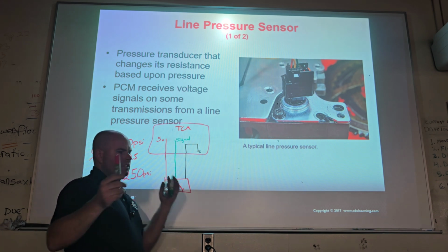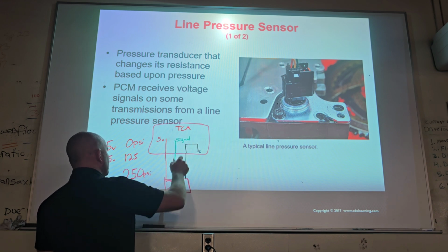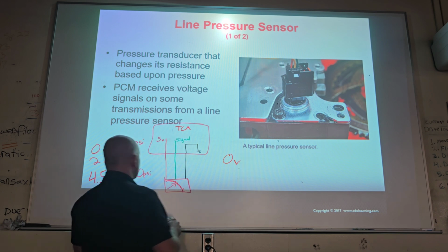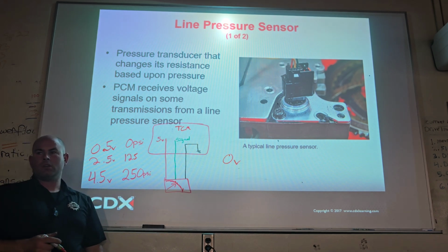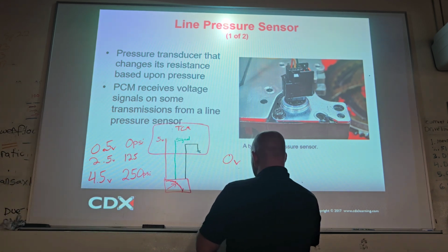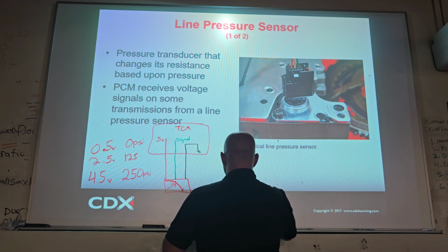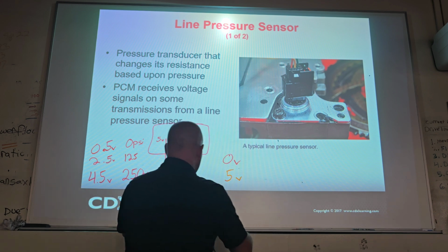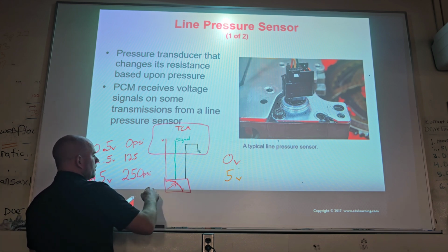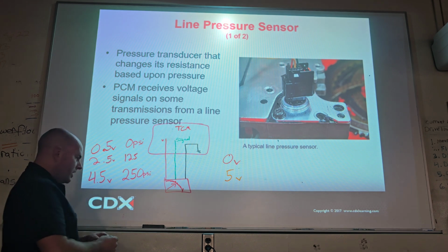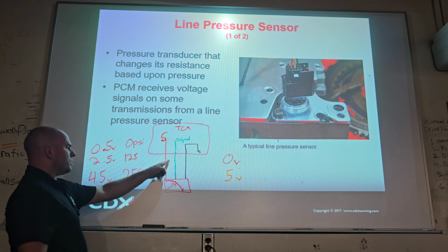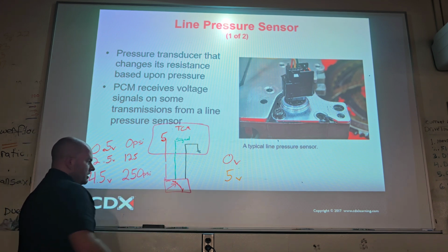If I get in the vehicle and it has some sort of DTC set and I look at live data and the live data says, let's go with 0 volts, when should it ever have 0 volts? Exactly. So remember, they're leaving these windows. 0 volts is no good and 5 volts is no good. How would we get 0 volts? Well, let's break it down. If we lost our 5 volts, there would be 0 right here. You understand? We could have a 5 volt bus down inside the ECU, and that would be a 0 volt reading, right?